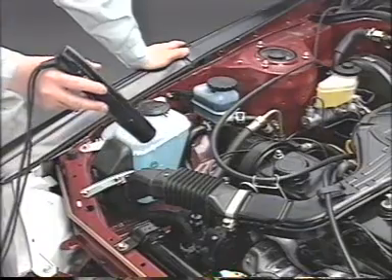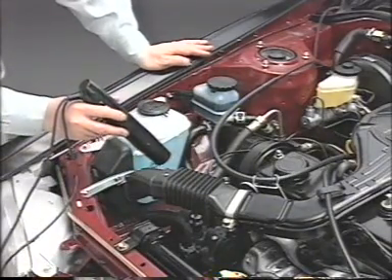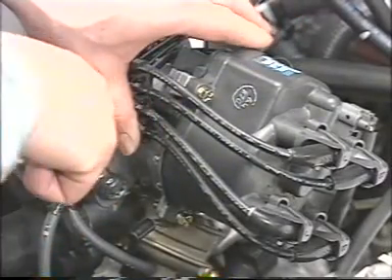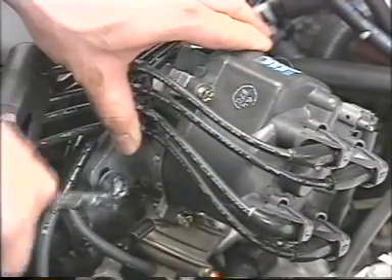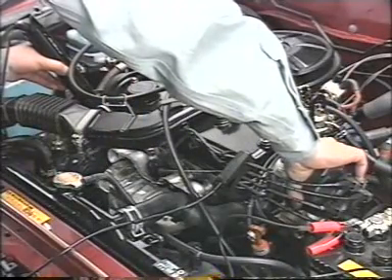With the engine idling as specified, use the timing light to check that the ignition timing is correct. If the engine speed is high at this point, the governor advancer will operate, so be sure to check this with the engine idling. If the ignition timing is incorrect, loosen the distributor bolts and turn the distributor.